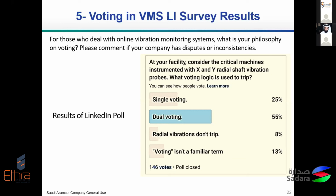It's not mechanical. Maybe it's a grounding issue in the circuit. Maybe it is a loose connection, things like this. And again, we have a vote here from LinkedIn. And according to the result of the vote, the majority of the people are using double voting. So they are using X and Y probes on the same bearing. They need to show high at the same time in order to initiate the trip. If only one of them does, it's not going to be a trip signal.